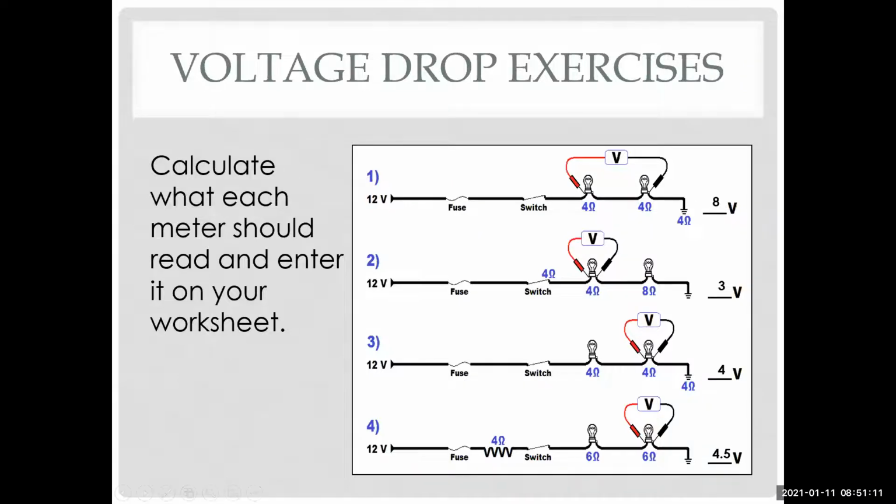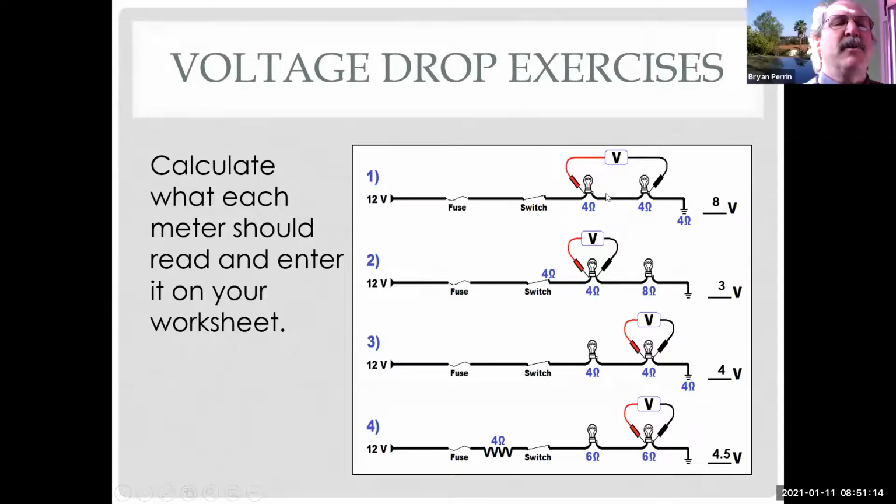Yes, I think so. So you can see where I might have a car that's overheating, even though someone's put a lot of parts into it because they're guessing. And the root cause is actually a bad connection to the ground or a bad connection in a wire or at a switch, causing the voltage to be lower. If the voltage is lower, the fan's going to spin slower and the car might overheat. So you see why it's not as simple as just putting parts on the car. It's about the electrical testing. That's why it's so important to verify that the correct voltage is available to the load.